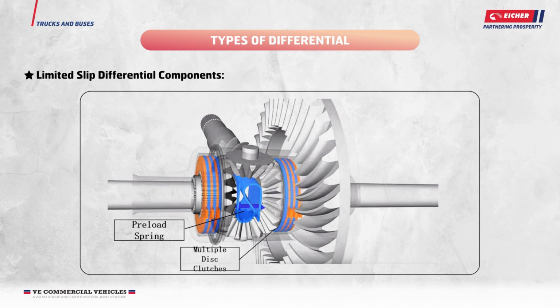Clutch pack: each clutch pack has the same number of clutch discs and plates. The clutch pack is designed to slip when some preset torque value is reached. When the vehicle is making a turn, a high torque, caused by the outer wheel rotating faster than the case, causes the clutch pack to slip.